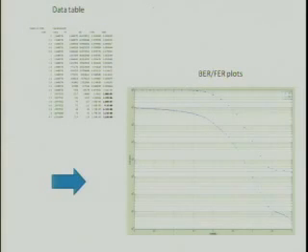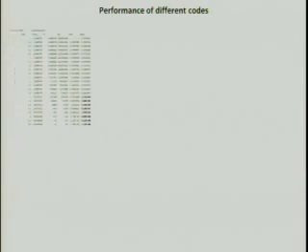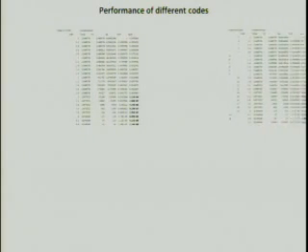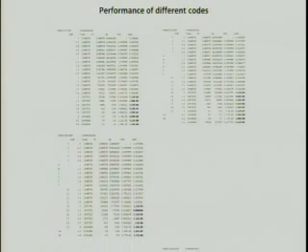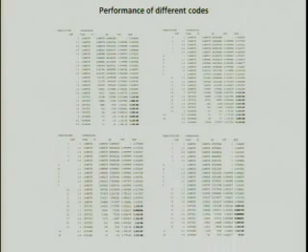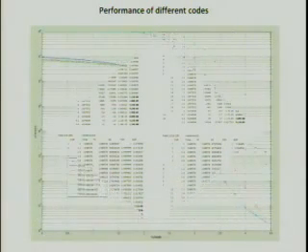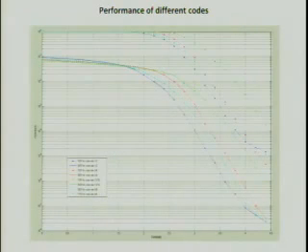This time, using the library I configured, I can easily adapt to different codes only by changing several parameters in the controller and the initialization files. Then I tried different codes for different rates: rate 1/2, rate 5/8, rate 3/4, and rate 13/16, and finally got their performance. In this way, we can easily compare their performance for codes of different rates, iteration numbers, quantization, and so on.